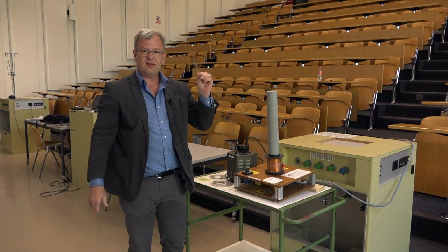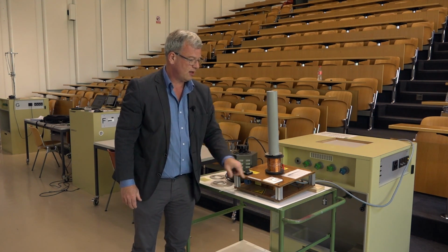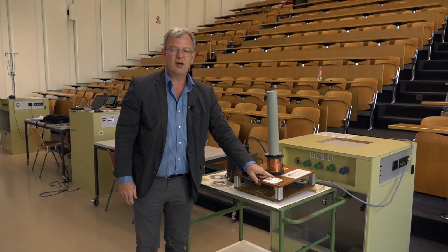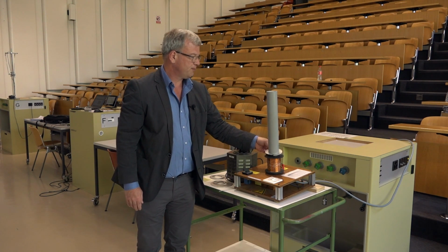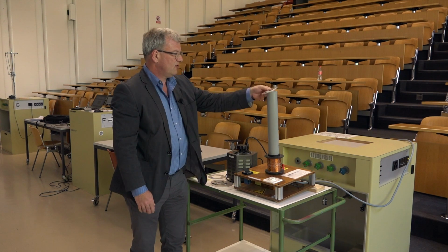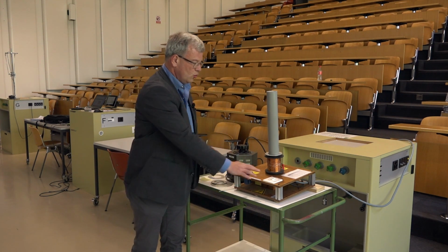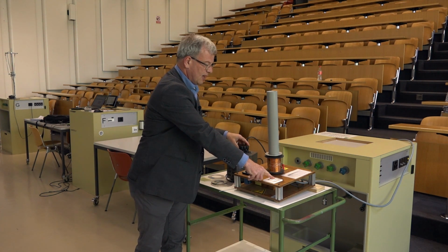Now the ring is cut and current cannot flow, so I'll do the same experiment here. Now we have no ring current, so there is no current that can flow. Push the button and nothing happens. Conversely, if I run an AC current through the coil here, then I have a change in magnetic flux, and as I increase the current, that is the change in magnetic flux, then the force acting on the ring increases.